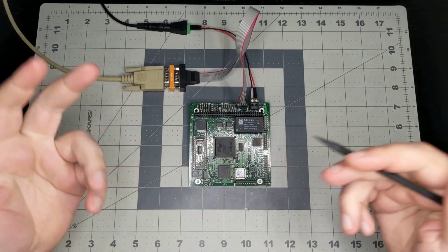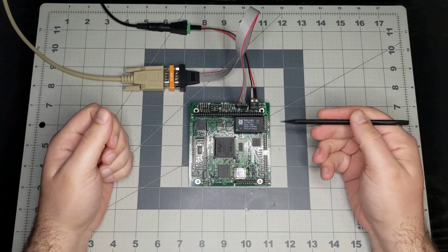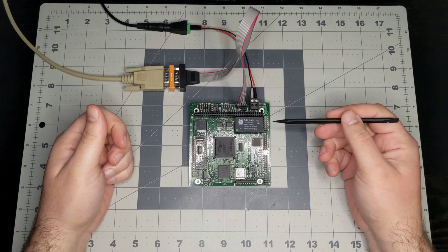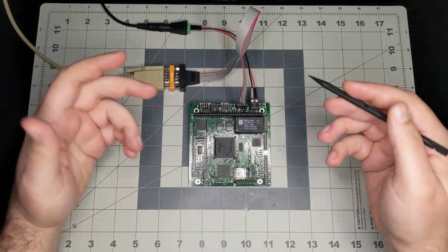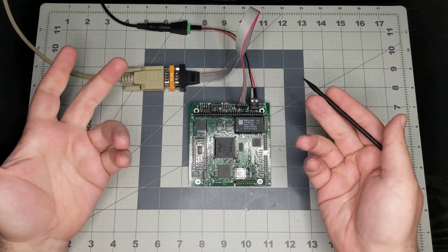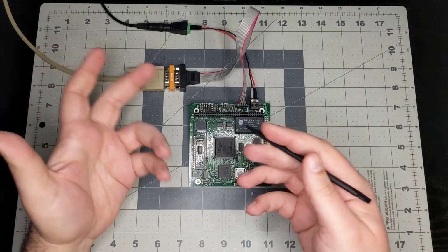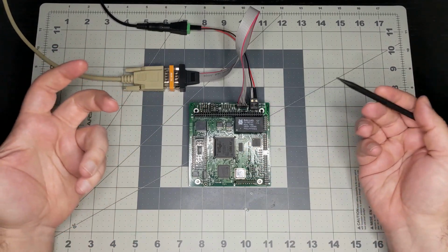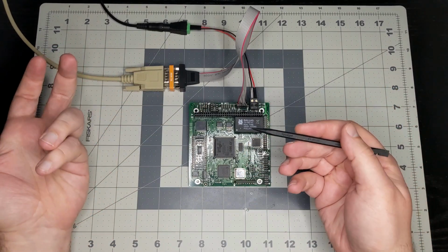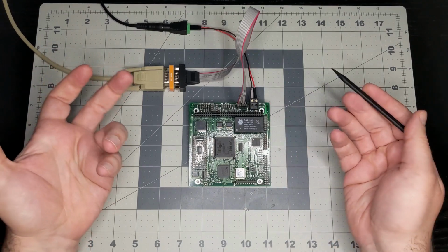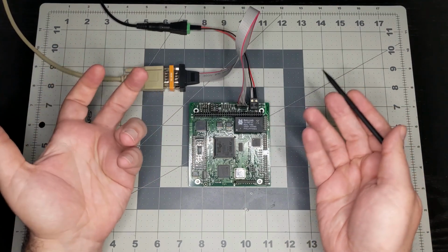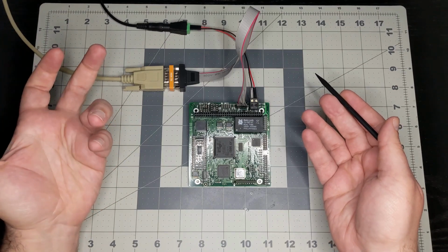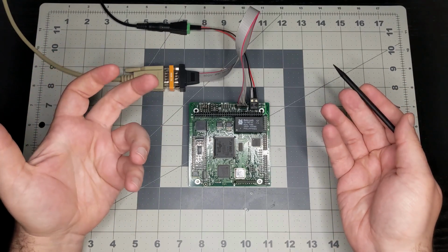Welcome back everyone. In the last video we took a look at a 386 based PC104 single board computer called the TS3100. It was a low-end DOS computer meant for replacing PCXT and PCAT based computers for embedded applications. I had a rather unusual problem with them where replacing the RTC module triggered a bug in the BIOS which caused it to erase itself, so we're exploring how to create a recovery tool that replaces the BIOS to let us reprogram the onboard flash.